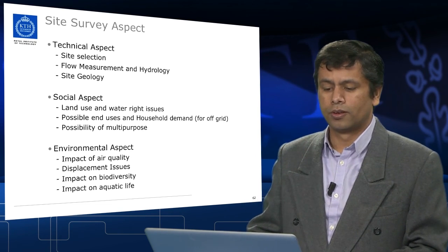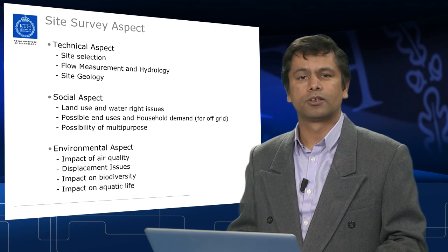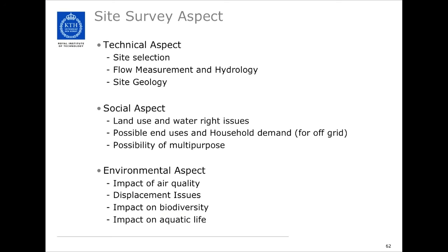Also, site geology is important to figure out: what kind of soil is available, and how the soil is structured. How deep your structure needs to go, and what kind of soils are there, also depends upon that. Some soils are not good for the structures, and that needs to be tested with the site geology.